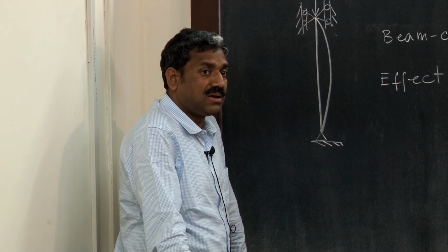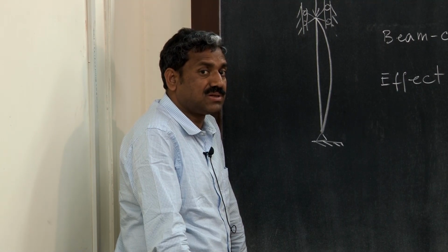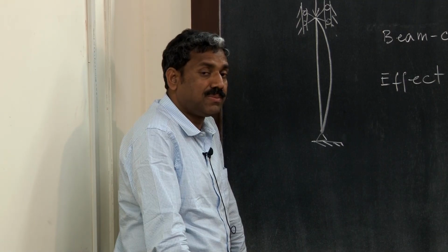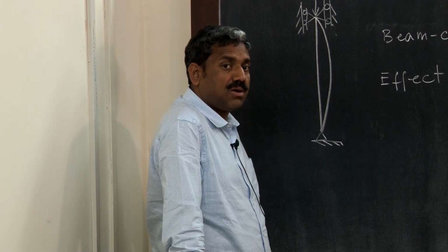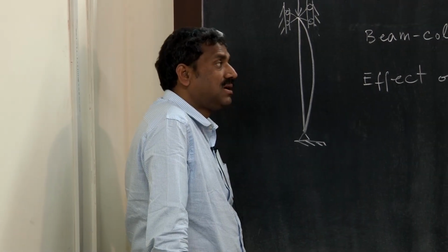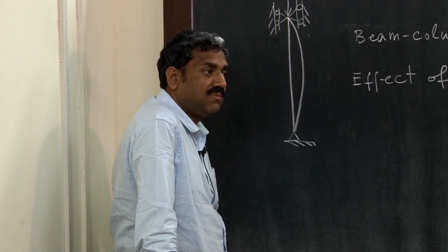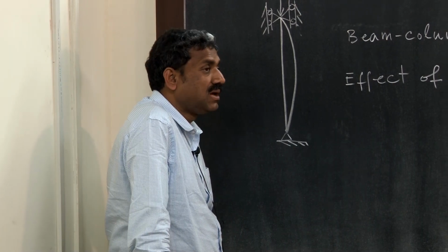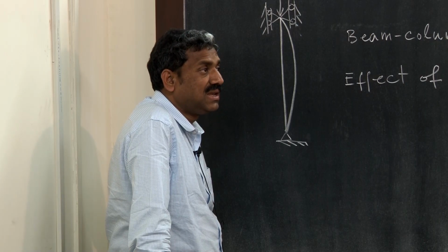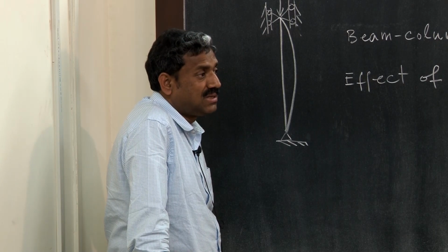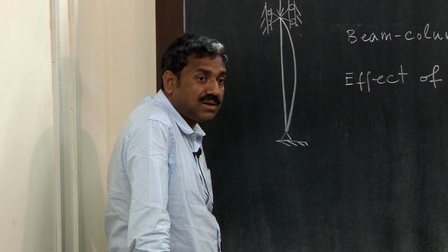But in a thick plate you have to consider shear deformation, and that assumption that plane sections remain plane is no more valid. You need to consider additional rotation of the cross section. That theory which includes the shear deformation is the Reissner-Mindlin theory. Similarly, for a thick shell, you will see the Naghdi theory, including shear deformation.